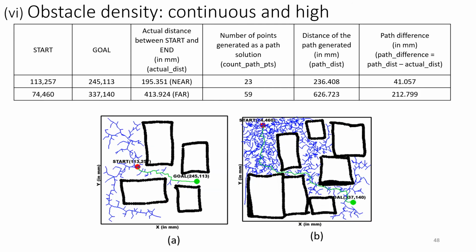Configuration 6. Here, a large number of big obstacles are present in the workspace. When the start and goal are near, the path generated is approximately a close fit path generated to expand in the reduced workspace and contour around large obstacles. So, the RRT search tree need not search and expand in the entire workspace. The minimum path difference attributes to the highly narrow search space facilitated by the many large obstacles.